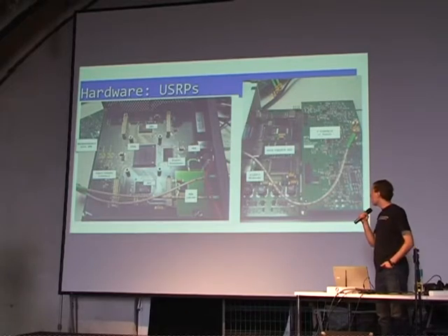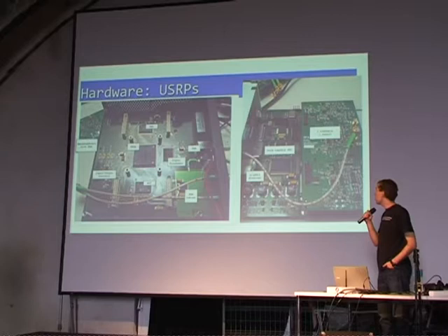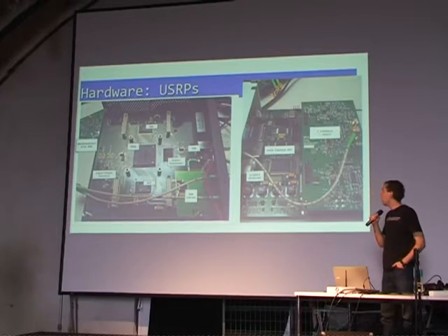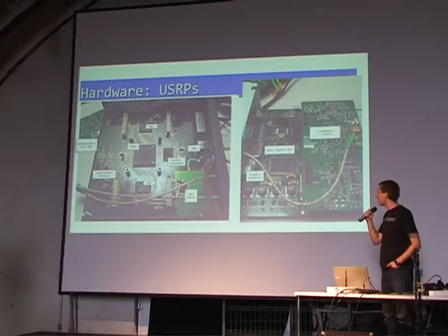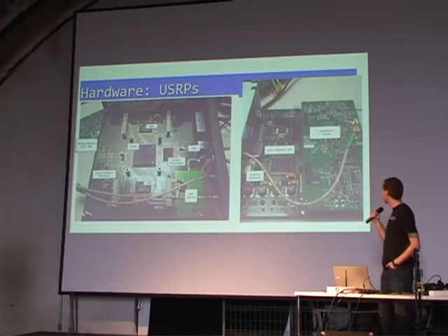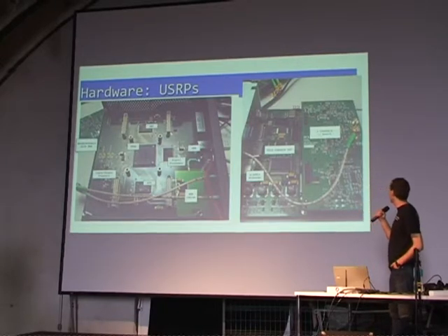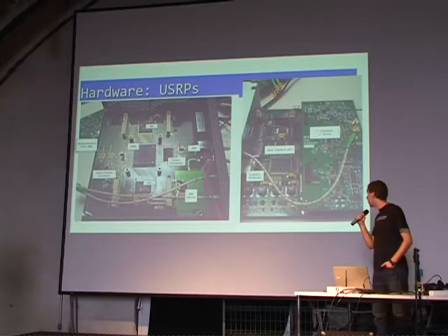You see SMA cables, a signal processor, an FPGA in the middle, which is the large chip. And that is the hardware which is practically powering the USRP1. For USRP2, which is the newer variant, you see that it has only 2 channels. So there is 1 daughter board added, but you have just 1 daughter board or 2 daughter boards using float sampling and not complex baseband sampling.